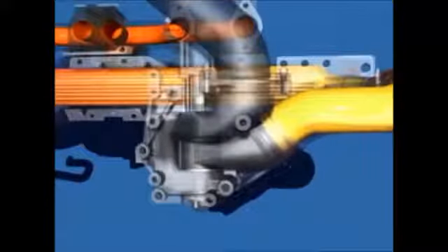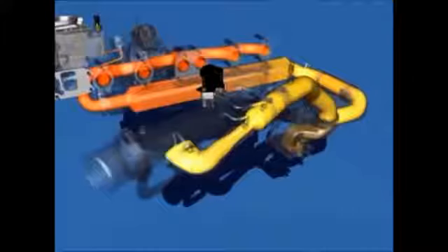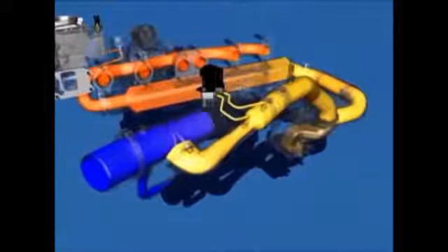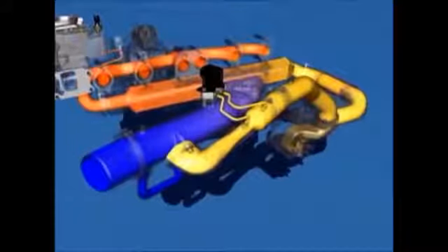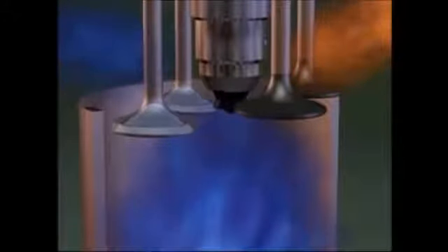When commanded to do so, the EGR valve opens and allows more exhaust gas to flow. The gas then flows through the EGR connection tubing toward the intake air inlet. On the intake side of the engine, the recirculated exhaust gas enters an inlet mixer. At this point, the compressed fresh intake air coming from the turbo is combined with the recirculated exhaust gas to form the charge air for combustion. This charge air then enters the intake manifold and then the combustion cylinders.